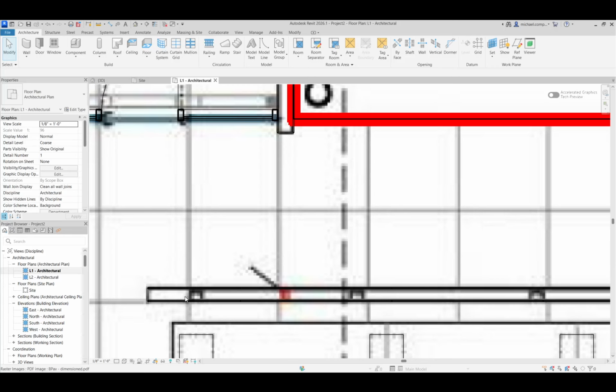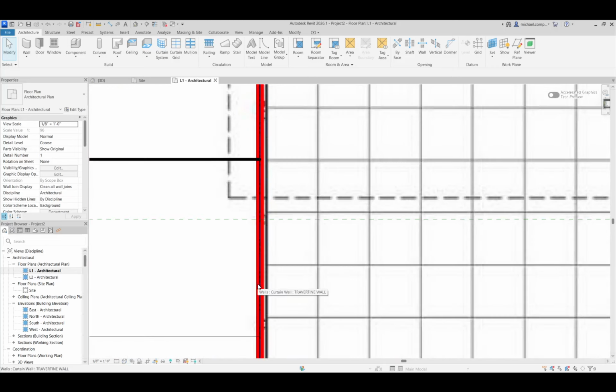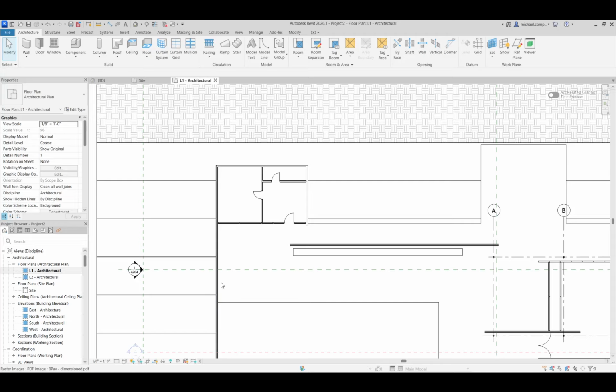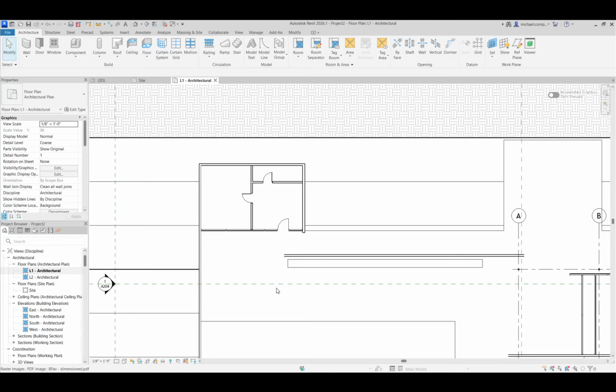In truth, it is a cavity, right? We have tubular steel studs or columns actually holding up these stone walls. And then there's a cavity and it's just a thin veneer of stone. So we're modeling it the way they would build it. But we're also doing that with the mass tool here, right? So the mass tool is right also, although you can't see it because of this. So the mass tool is also a thin veneer with a void. So you're probably like, well, what's the difference?